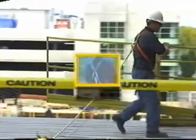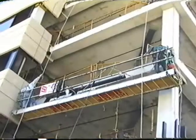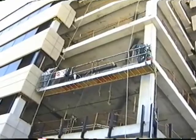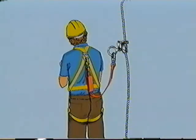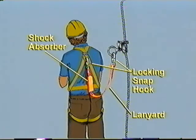When fall prevention is not practical, you must use a fall arrest system. A fall arrest system doesn't prevent a fall, but it limits a fall once it occurs. The system must be set up to keep a worker from striking any object or surface below. A typical fall arrest system consists of several engineered and certified components, such as an adjustable full-body harness, with a built-in attachment point for a shock-absorbing lanyard.